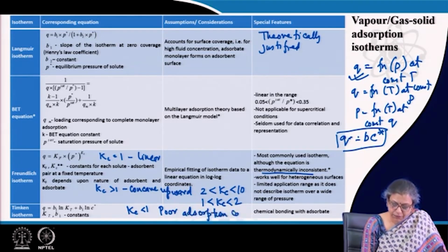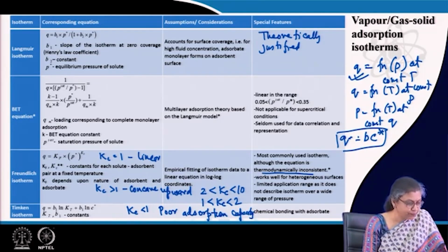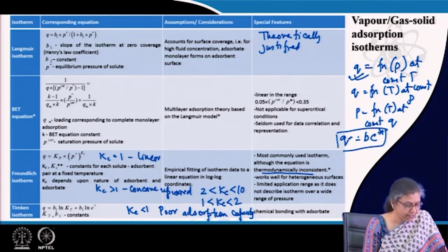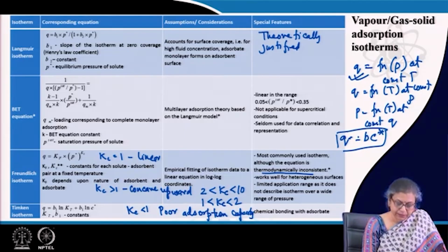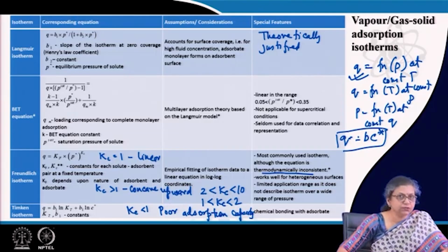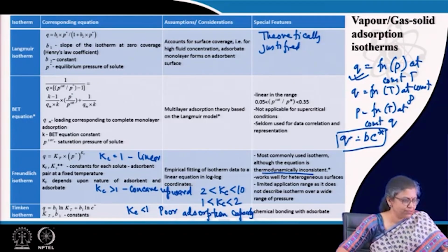So, if we would like to select an adsorbent, we would like to ensure that the Kc value is greater than 2. In that case, it represents that the adsorption is going to be effective. And we definitely do not select any adsorbent which yields a Kc less than 1. Well, with these things said, we have discussed adsorption. The next thing is liquid extraction.